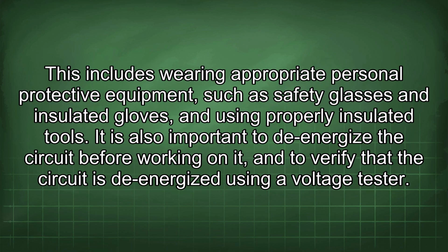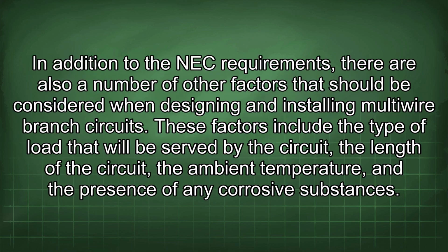This includes wearing appropriate personal protective equipment, such as safety glasses and insulated gloves, and using properly insulated tools. It is also important to de-energize the circuit before working on it, and to verify that the circuit is de-energized using a voltage tester. In addition to the NEC requirements, there are also a number of other factors that should be considered when designing and installing multi-wire branch circuits.